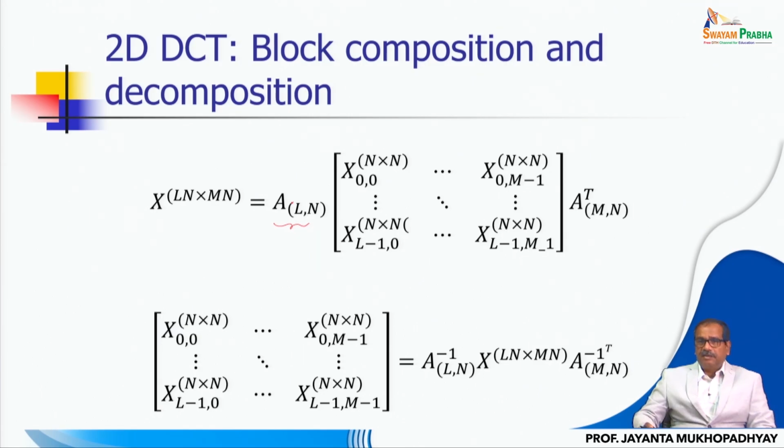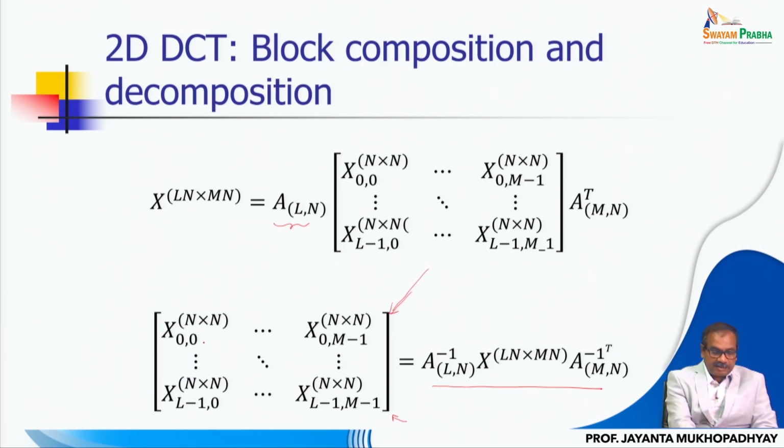So in one dimension I can perform this inversion, and for two dimensions your expression looks like this, because if I apply this inversion in this form, you will get back the n cross n blocks of L cross M from a larger block size. From a larger DCT block, you can get smaller DCT blocks with these spatial arrangements.